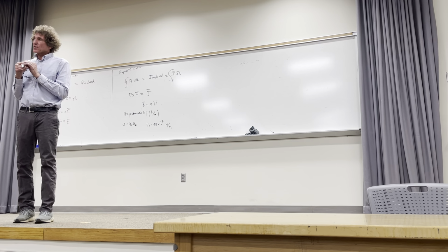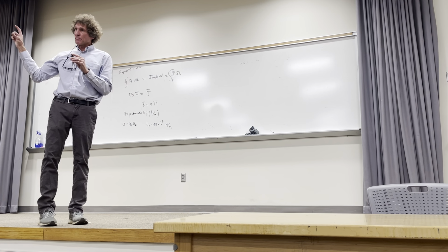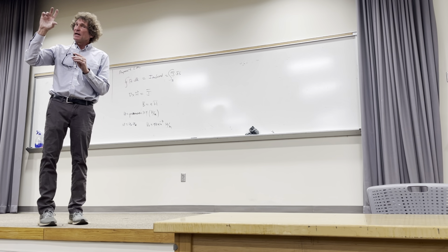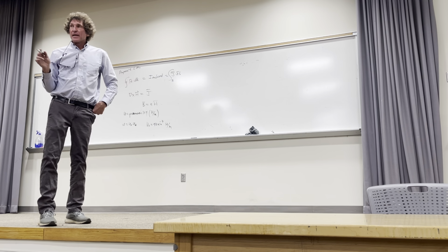Most of the time in your work, you assume the transformers are 100% efficient. Power in, power out: VI primary, VI secondary. In other words, that's not quite true. There are losses, and you do have to account for them.